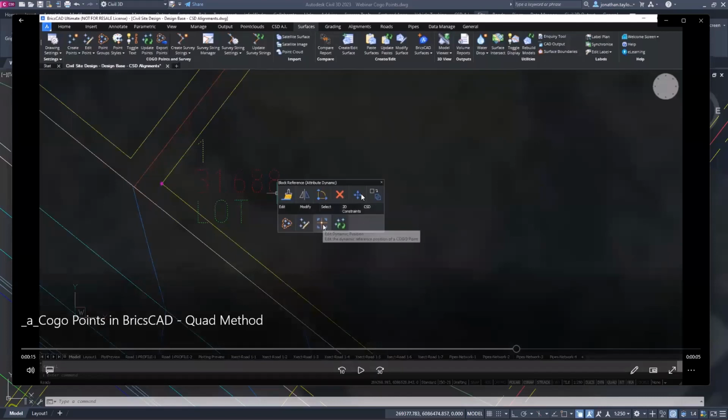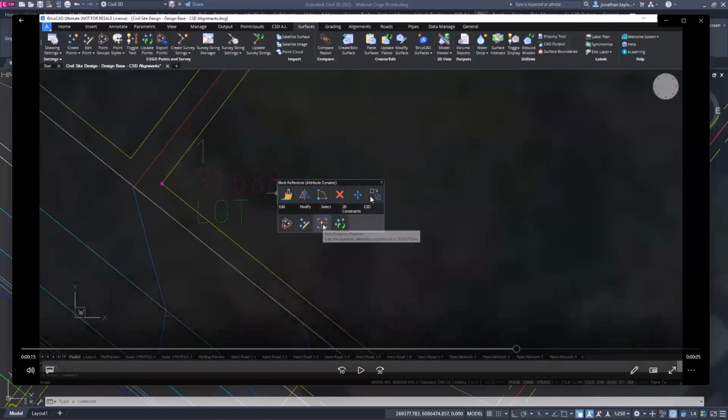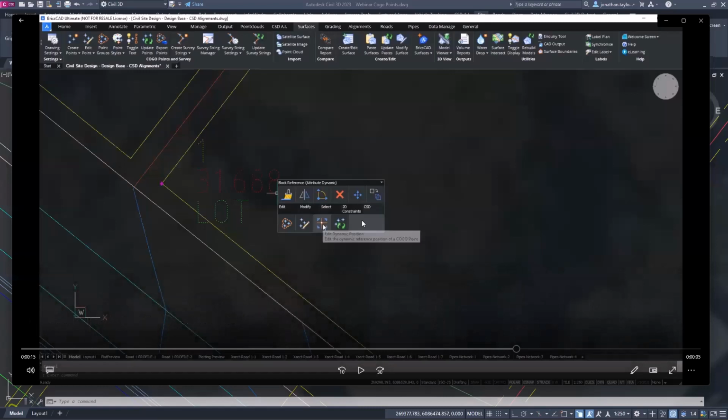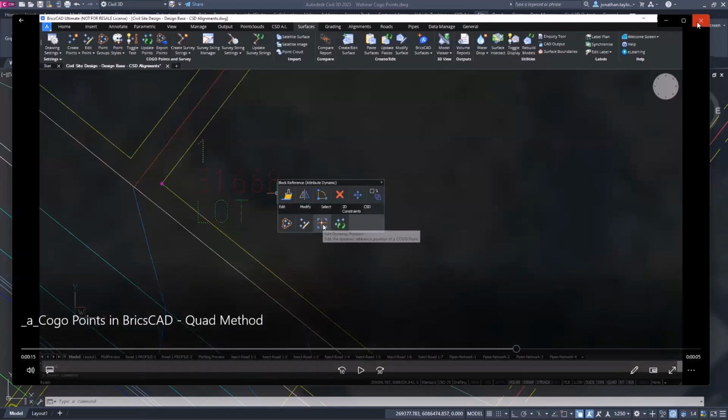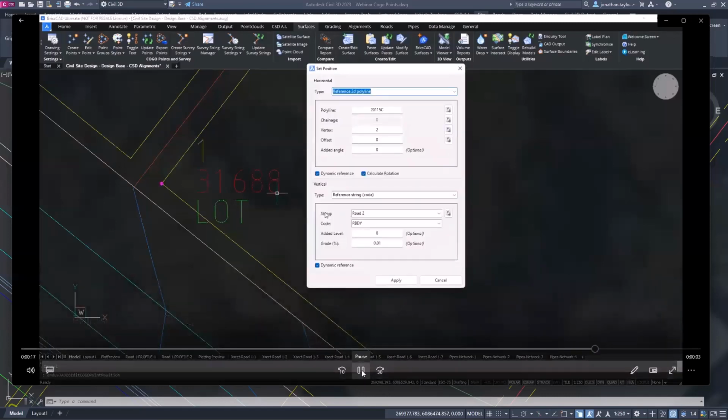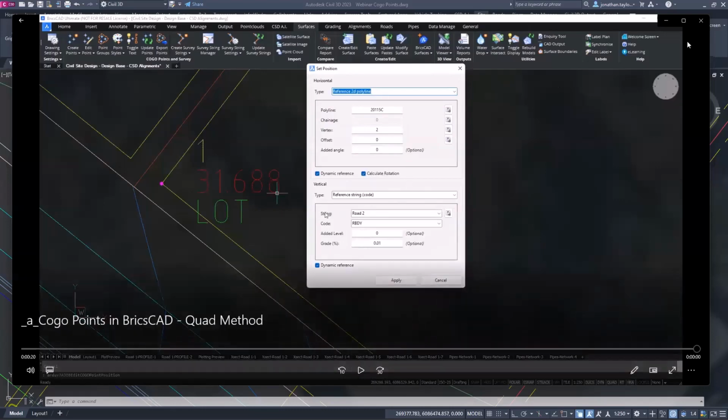You get a contextual ribbon on civil site design objects. So if you're on a civil site design string or on a civil site design surface, this quad menu actually updates and will provide you with contextual items related to that particular tool. The main reason is because we've obviously got a lot of these tools through the grips for the AutoCAD users, and you can't access those tools in the same way in BricsCAD. So the quad is your mechanism to get to those particular features, which you can see it does here.